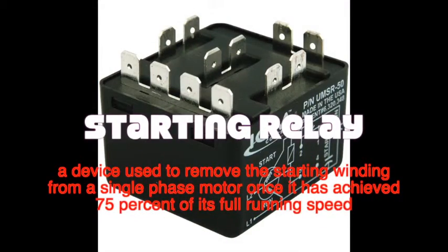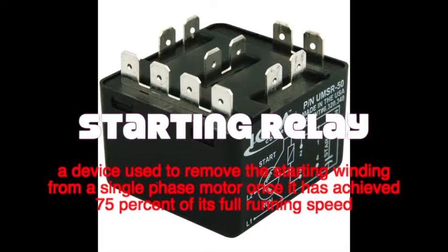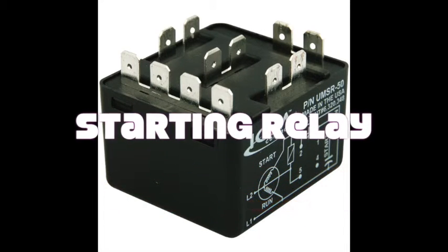Starting relay: a device used to remove the starting windings from a single-phase motor once it has achieved 75% of its full running speed. That's a starting relay.